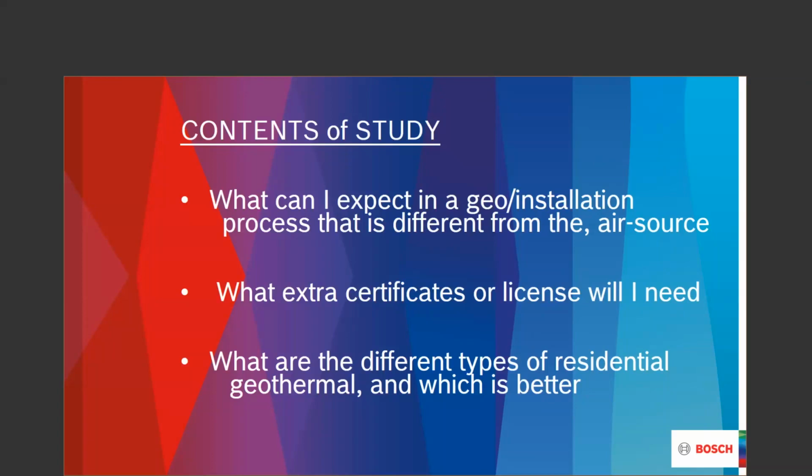Remember, when I talk about the open loop, I never say that a Bosch geothermal system in an open loop application uses water. It does not use the water; it utilizes the water. If I use the water, that means I would take that 1.5 gallons a minute, flow it through the machine, and then I've used it up. Well, I'm utilizing that water, so whatever water came through that heat exchanger is now going to be expelled out of that heat exchanger into Mother Earth somewhere. So again, we're just utilizing Mother Earth's water.